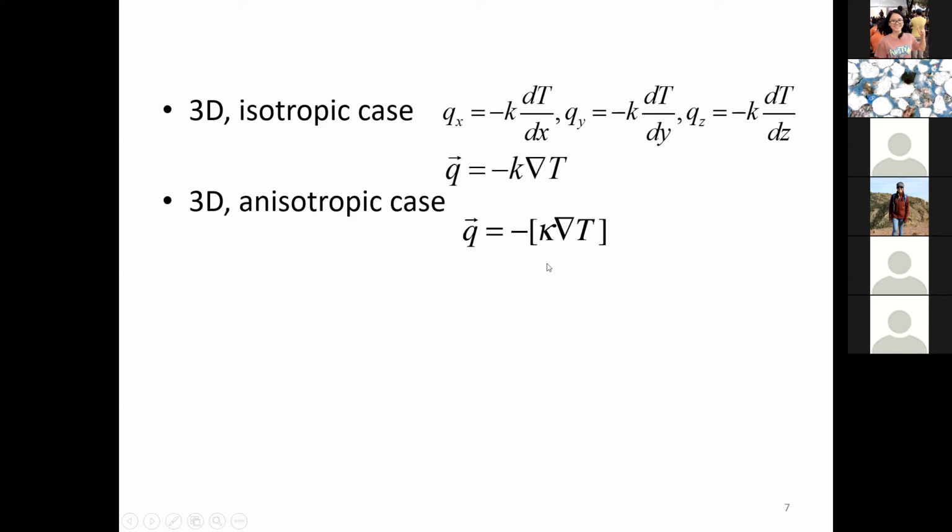Okay? In some sort of anisotropic case, this K would be different across different planes in different directions and essentially described by a tensor. And in which case I would have that tensor multiply gradient of T. So this is again not so commonly used in applications, or we simplify our solution to the layers where things are homogeneous. However, there are media, in porous media, that are anisotropic by default.